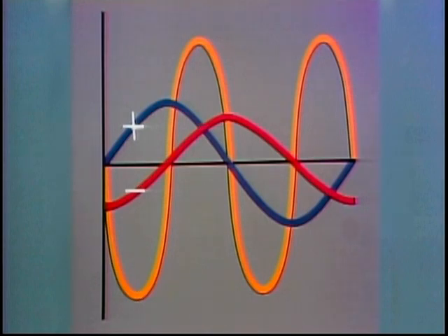In the first portion of this sine wave, voltage is positive, but current is negative. If we multiply voltage and current together to get power, we get negative power, because the product of a positive number and a negative number is a negative number. During the second quarter of a cycle, voltage is still positive, but now current is also positive. Since we have two positive numbers to multiply together, power for this portion of the curve is positive.